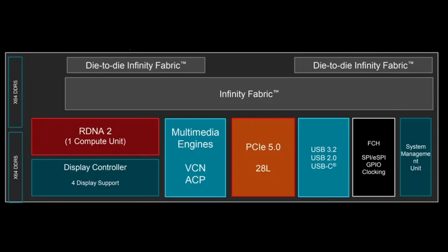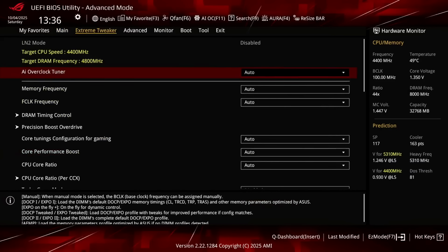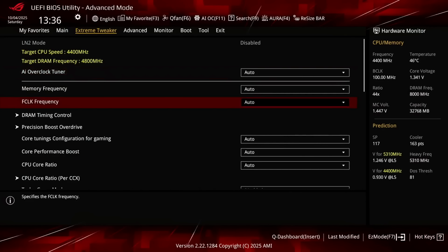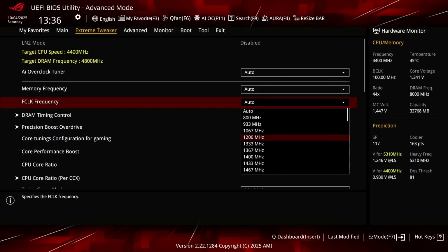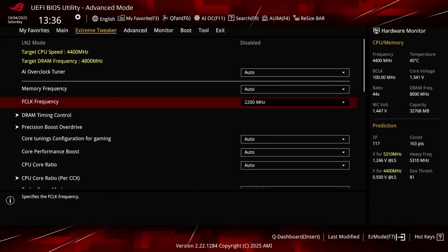Tuning the Infinity Fabric probably has a minimal impact on graphics performance because the graphics IP block is on the I/O die, just like the memory controllers. That said, it doesn't seem there's that much overclocking headroom beyond 2 GHz. I managed to set 2.2 GHz for this overclocking strategy, however anything higher couldn't boot reliably, not even with voltage